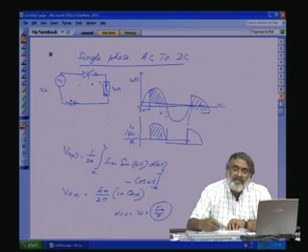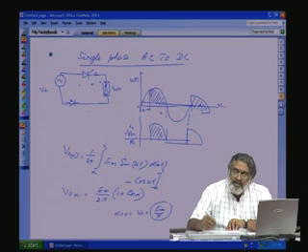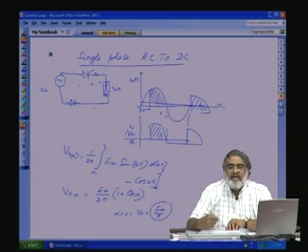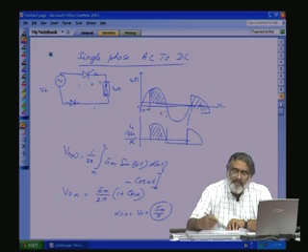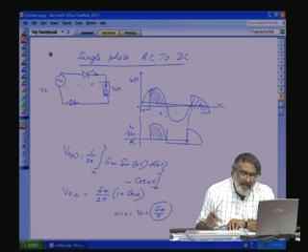To put a filter means it is a cost-effective proposition. So, for inductive loads, as the frequency of the voltage waveform is high, the impedance of the load, that is L omega, will increase, and the voltage divided by L omega, the high amplitude harmonic current can be suppressed only by the motor inductance. But what we are interested in is the DC part. So, this value gives the DC value.